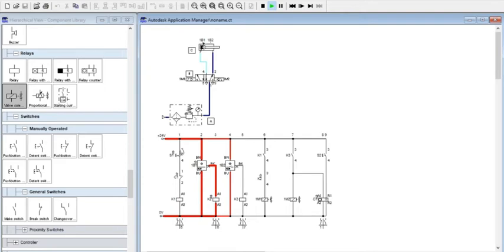We can see here the D10 switch changes from normally open to normally closed. When the D10 switch is pressed, there is no electrical flow through proximity switch 1B1 because the contact inside changes from normally closed to normally open. The coil of relay K2 is de-energized.